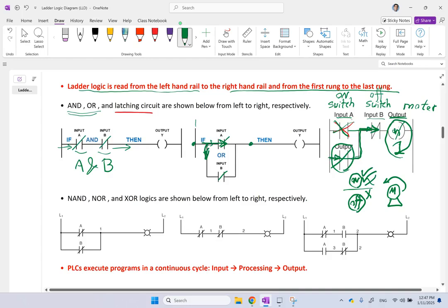That's where you press on this off button. When you press on this, since this is normally closed, it becomes normally open now. This guy becomes normally open. And even if this is normally closed, guess what? Because this is open, regardless of what A is and what output is, the electricity will stop here. So this guy goes to 0, then this guy goes to 0.